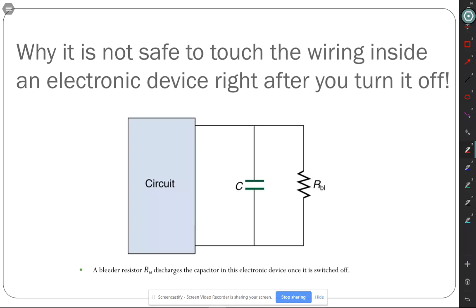Second deadly thing is dealing with the heart. If you have a current that goes across the heart and it's more than, say, 50 to 70 milliamps, then it can cause currents to go wrong in the heart. Or you can cause the heart to seize if it's too much. And so, if you have a consistent current going across the heart, you're going to make bad things happen.